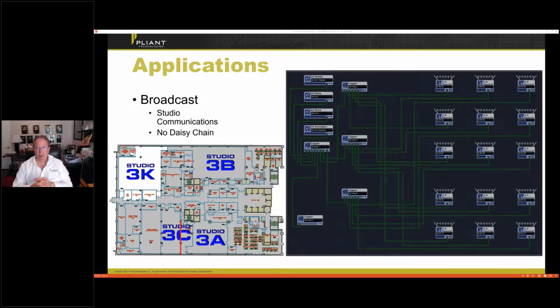They're using both frequencies. We've coordinated them carefully and adjusted antenna gains and such, so everybody plays nice together. So even though we have the ability to build up 14 transceivers in 900 and another 16 in 2.4, because of our ability to synchronize, we can have multiple systems operating in the same area. And just like good RF, it just needs a little bit of design.